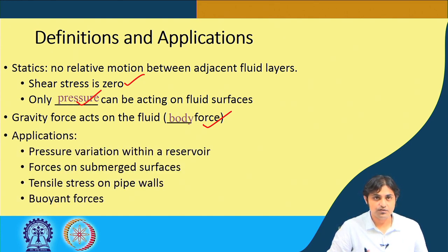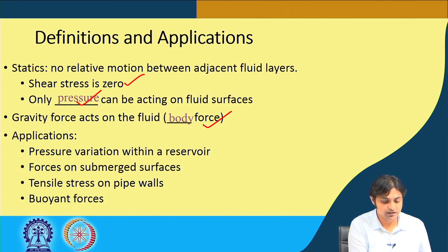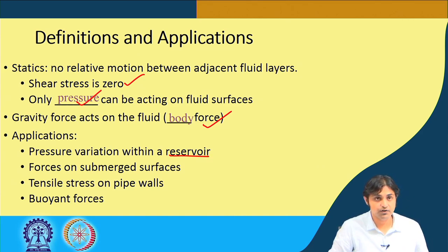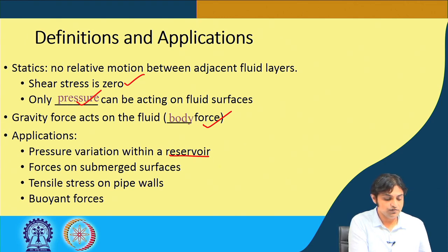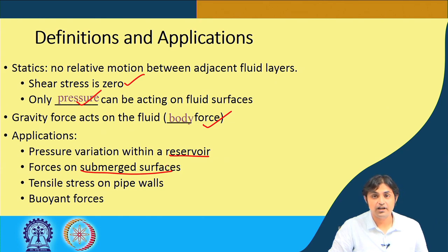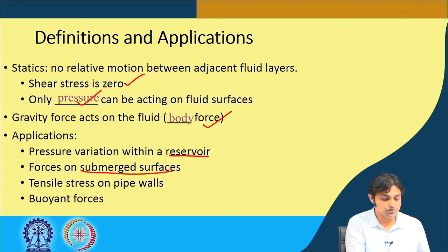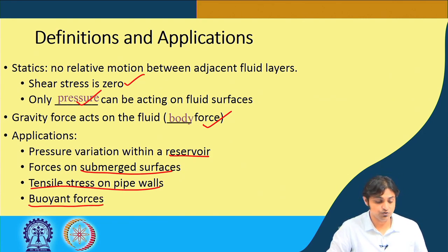What are the applications of what we are studying about pressure? We can know the pressure variation within a reservoir, so it finds application in reservoirs. We are also able to find forces on submerged surfaces. You will see many cases in real life where the surfaces are submerged. We are also able to find, using this principle, the tensile stress of pipe walls, and we are also going to see the buoyant forces, because buoyancy plays an important role in this.